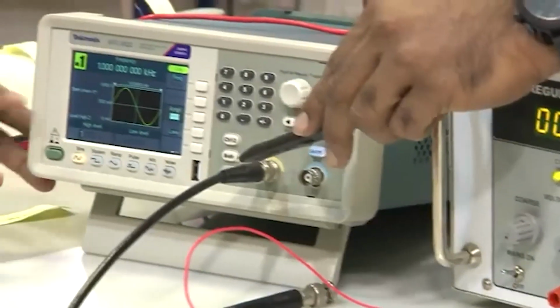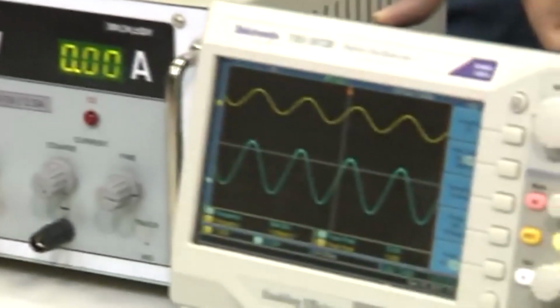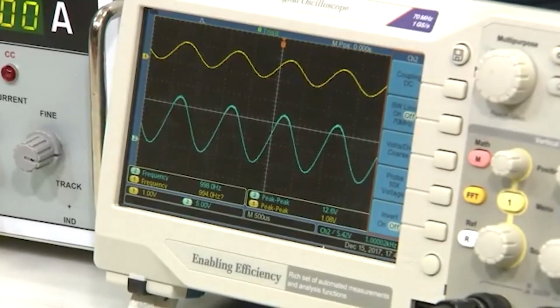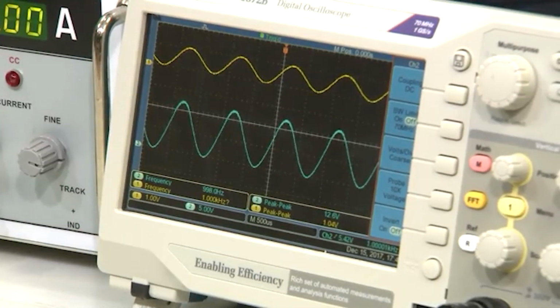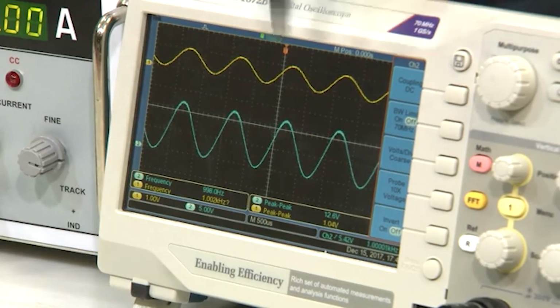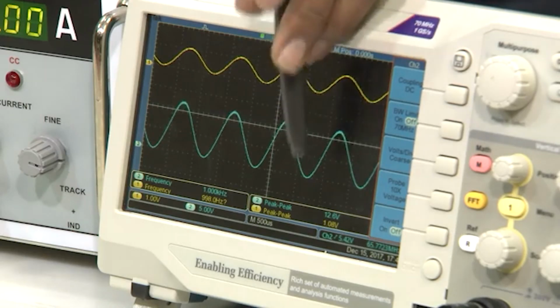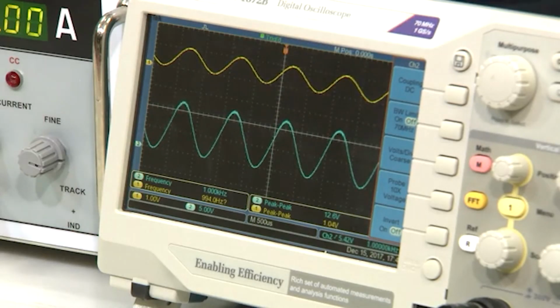So when you connect your frequency generator, now we are applying sine wave, right. So we have to now see the oscilloscope. What we see is the amplification of the signal: sine wave of 1 volt, 1.04 is the input, around 12 volts is the output. Phase shift 0 degree, very easy, right. If you say inverting, phase shift 180; non-inverting, phase shift 0 degree. Both are amplifiers, so there will be amplification.